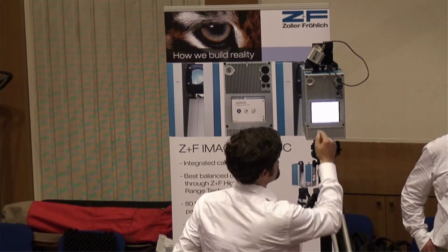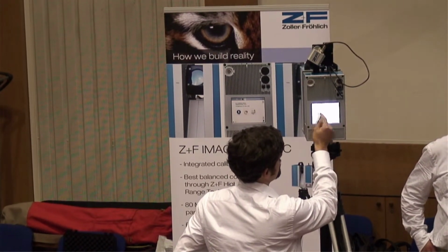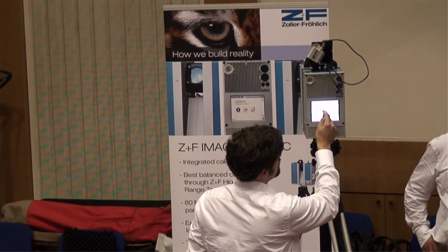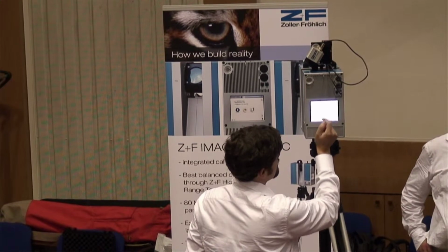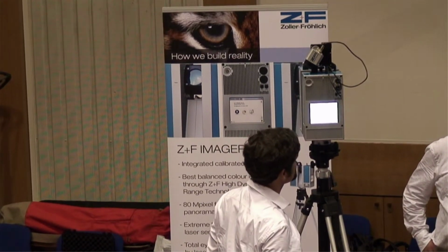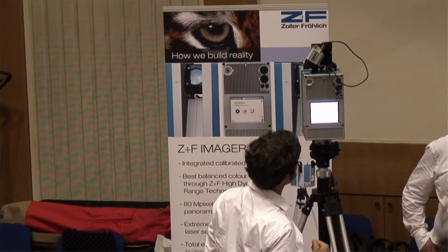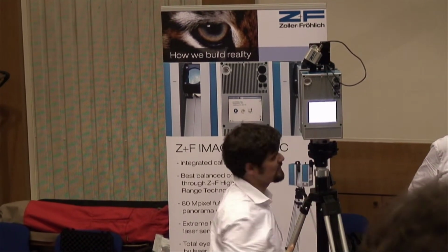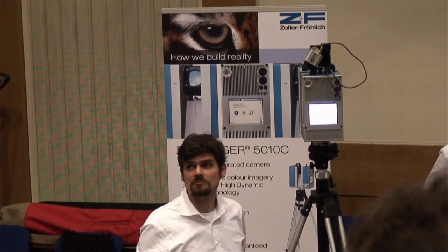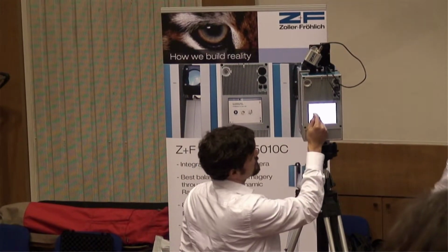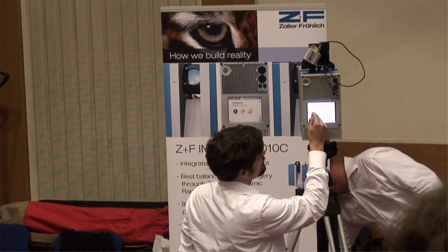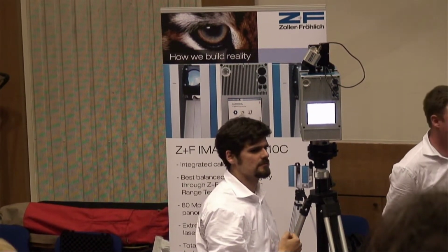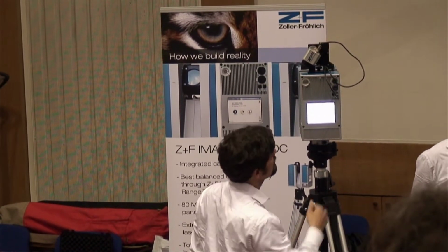Most important here is the resolution, that's this little button here. You've got various settings from preview to extremely high. You're not at ridiculously high yet, but maybe next version. Extremely high would be 6 millimeters over 100 meters, while the preview scan is about, I think, 5 centimeters on 10 meters. So it's a pretty coarse resolution.